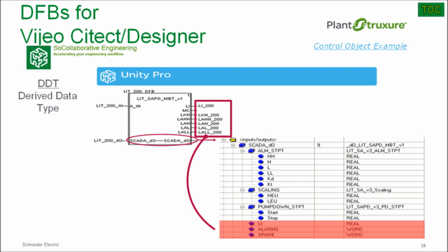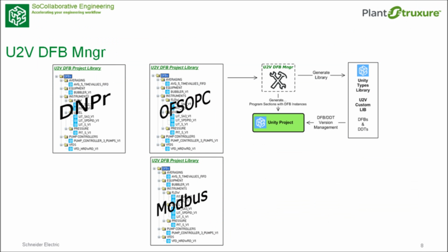But allow me to address other aspects of the overall solution that could be optimized. Communications bandwidth requirements, PLC memory usage, PLC scan time. These all have costs associated with them. Eliminating irrelevant or duplicate data and useless code is best. So rather than worry about managing multiple versions of very similar DFBs, consider this alternative. The DFB Manager makes it easy. Simply create a DFB library for each of the protocol situations. Boom, done.